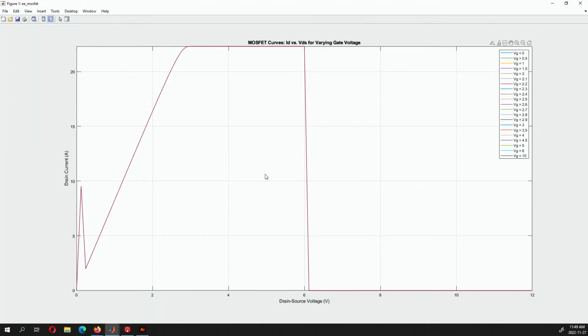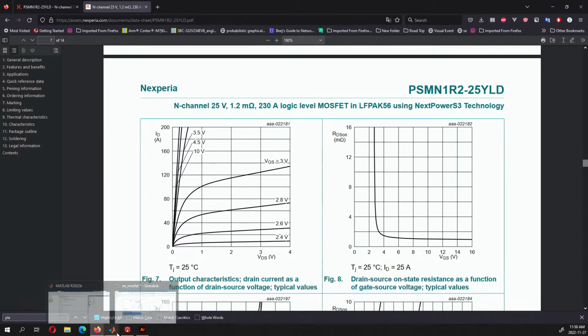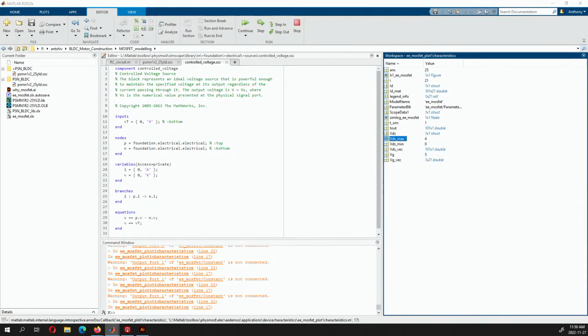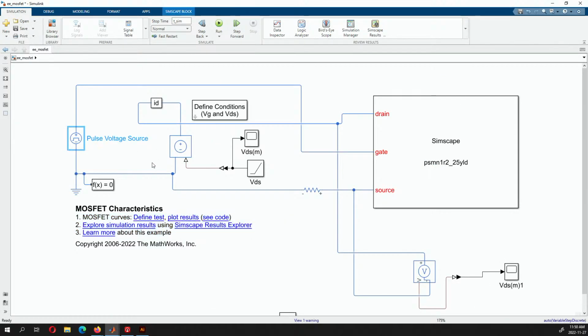Now, this is not coming out particularly well. The red is at 10 amps, because that's what we have over here. In simple English, it's basically turning on. It takes some time to turn on, and then it turns off. This is because we have a turn on of 50% duty cycle high and 50% duty cycle low. So this is basically the turn on of the drain current. Ideally, it would give you this particular graph, but because I'm pulsing it over here, it's not the perfect schematic to represent that particular voltage.